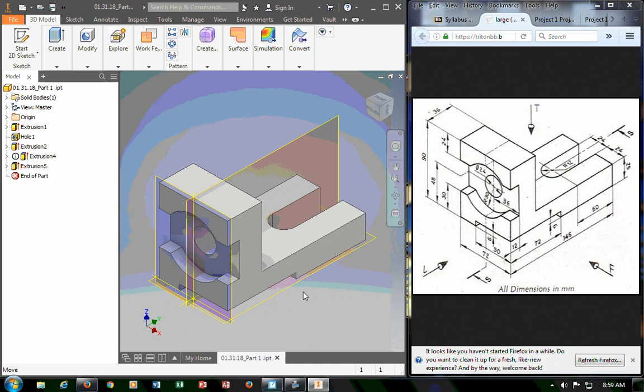This is the model itself. There's the drawing. It is in metric. Okay, so this isn't a standard third angle projection drawing. The model was built correctly in first angle projection. When you go home in first angle projection, bottom is upside down, right's on its side, and front is still there. Okay? That's one of the visual differences when you're in metric part.